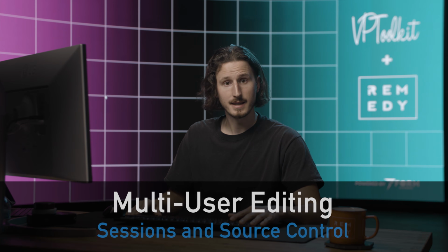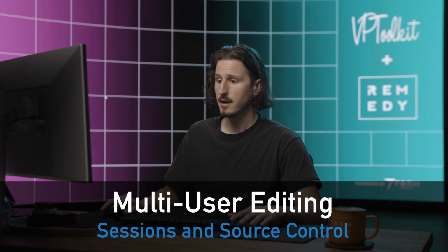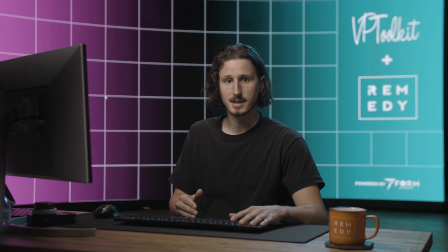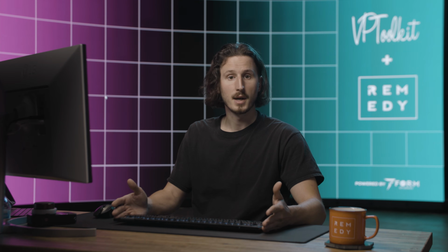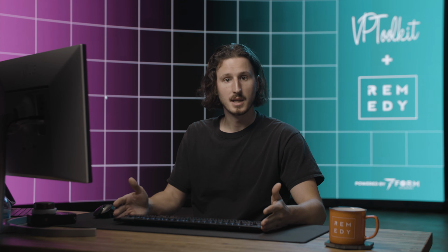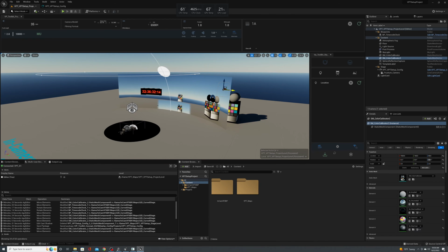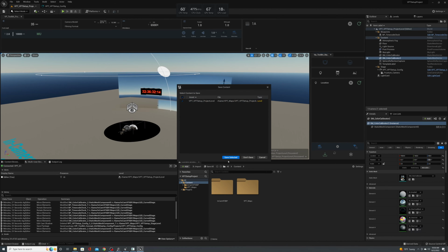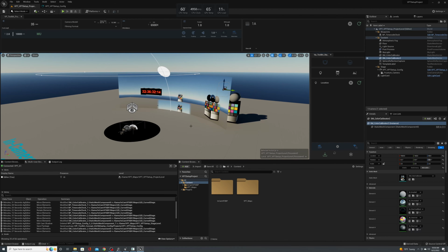So what multi-user is, is actually a form of source control. What it's doing is logging your transactions. So every time you move something or change a setting, it is logging that and then sending it to your other machines that are connected into the session. This keeps all of your projects that are in your multi-user session up to date and synced. This does not save to your local copy of your project. So if you are in a multi-user session and you hit save, that does not actually save your project. It just sends any transactions over to the nodes that have not been synced.